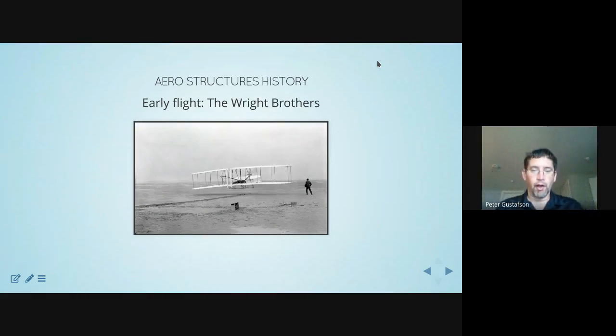Okay, so last time when we ended, we were talking about the scaling laws, this sort of adverse law of the length versus area versus volume, really first discussed in the literature by Galileo, but still very relevant and challenging to this day. What that amounts to is that the mass of something tends to scale as its volume, whereas the strength of something tends to scale as its area. So one goes as length squared, one goes as length cubed. And so that can cause some challenges.